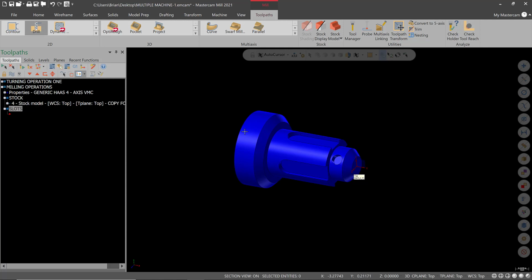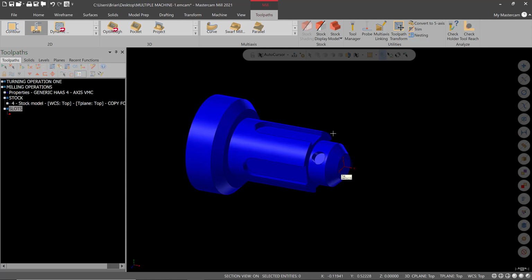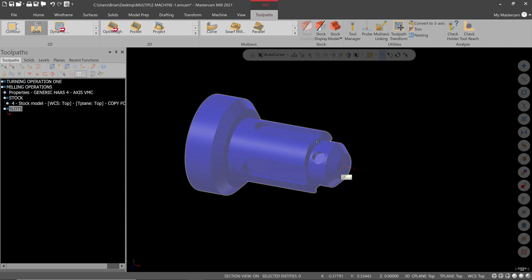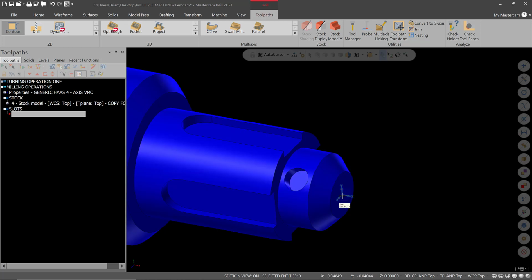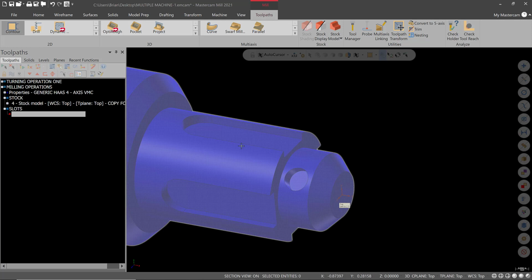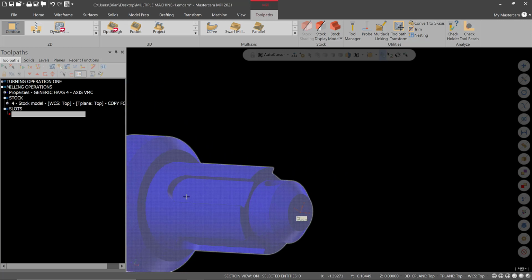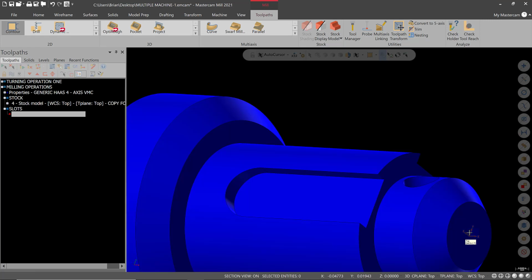All right. And then what we'll do, I'll transition here or pause, and we will mill these around. All right, so let's do a simple contour operation to cut these slots around. I am going to just chain one, machine one, then transform toolpath. Now one thing you got to watch out for is, it's not going to let you really chain in here easily because this is the y-axis. We need to look on this one here, because this plane is perpendicular to the Z.